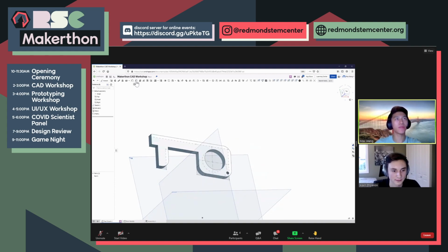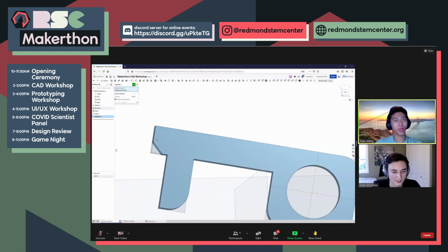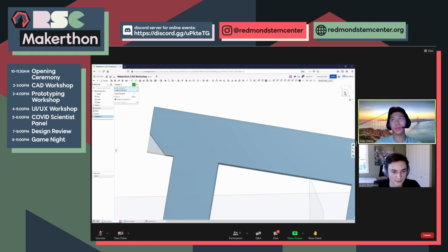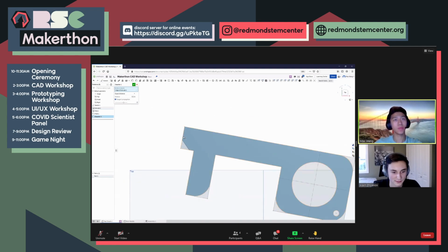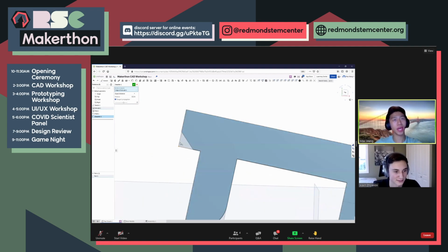Let's also go use the chamfer tool. This is the chamfer tool. It's right next to the fillet tool. It looks pretty similar, except you can notice the chamfer actually has a flat edge instead of a curved edge. So you might assume that it's going to cut a chamfer into it, which is what it does. It just cuts a flat surface into this edge. So where it once was this square-like shape, now it's like a pentagon, I guess, because it cut a flat edge to it.